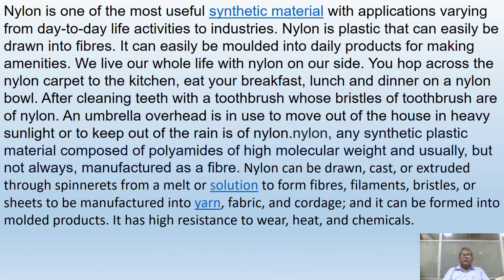Nylon is another useful material with applications varying from day-to-day life activities to industries. Nylon is a plastic that can easily be drawn into fibers. It can be easily molded into daily products for making amenities. Nylon can be drawn, cast, or extruded through spinnerets from a melt or solution to form fibers, filaments, bristles, and sheets.